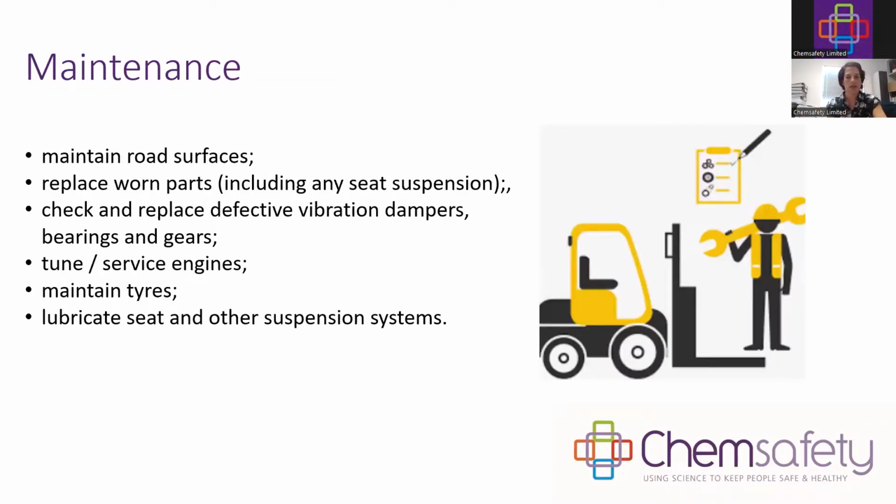And then maintenance. So you want to maintain the driving surfaces. You want to maintain your mobile equipment, because the more damage to, say, the shocks or the wheels, the more likelihood that vibration might increase. So regular checks of your mobile equipment, regular servicing, regular maintenance, that will help reduce the risk of that. And then you want to lubricate the seat or other suspension systems to ensure that they are working as they should.